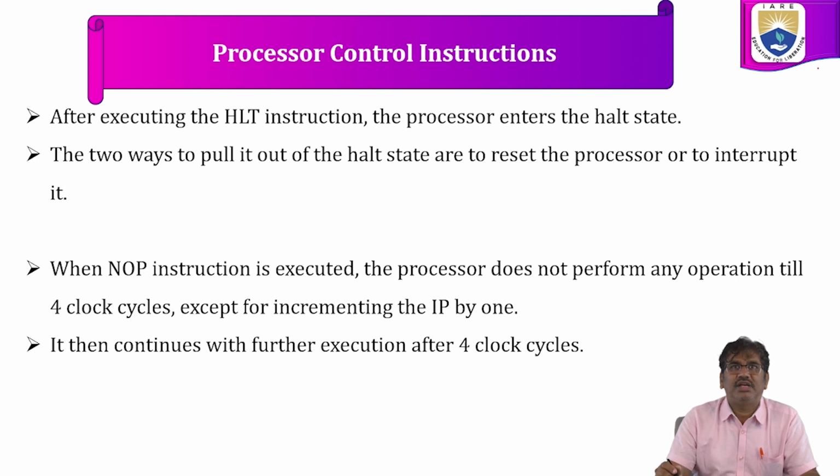After executing the halt instruction, that is HLT, the processor enters into the halt state. There are two ways to pull it out of the halt state: reset the processor or interrupt the processor.